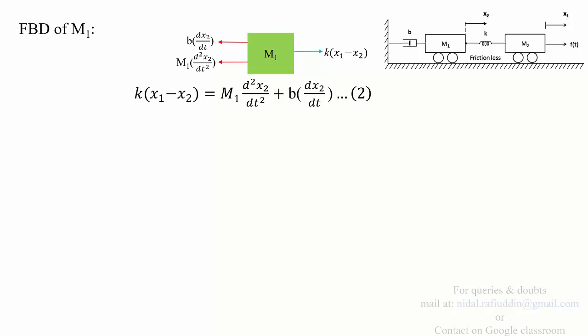So there are two ways of knowing how many state variables the system has. We discussed both of them. One is the way most of the books say, that the best way or the most accurate way for picking the number of state variables is to look into the differential equation associated with the system. And books also say that by looking into the number of energy storing elements, you can conclude how many state variables it could have. So that again depends upon what situation you're talking about.